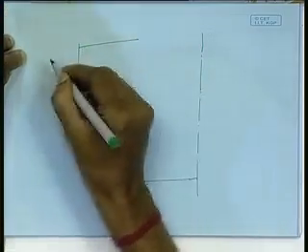It also contributes, it also undergoes the longitudinal bending. What you are saying is correct. So, by providing a gentle curvature, it does contribute to additional strength, true, but the primary purpose is something else. Drainage, simple drainage of water. There is no harm if I make it horizontal, and the necessary strength I provide by means of stiffening members, right. But it is given such that water naturally drains out on the sides.